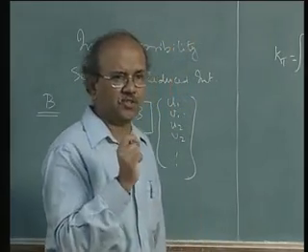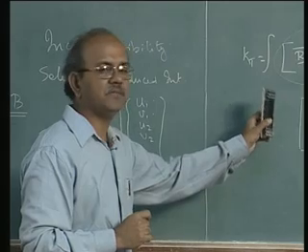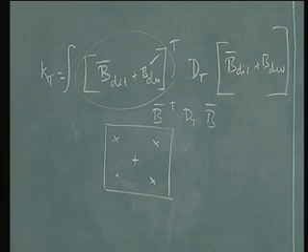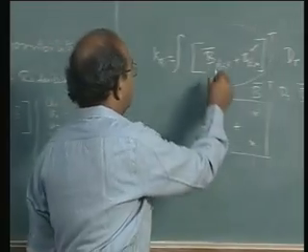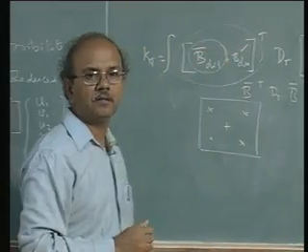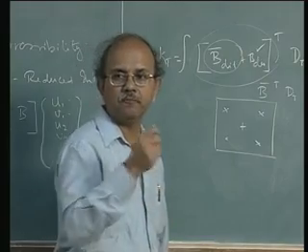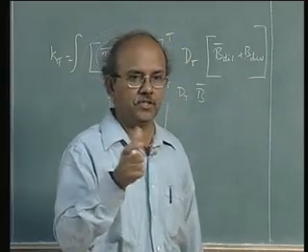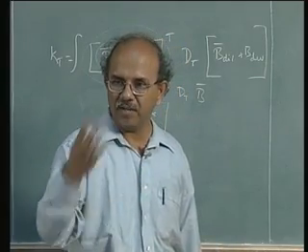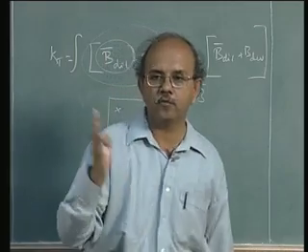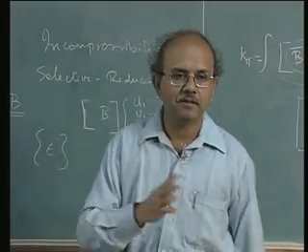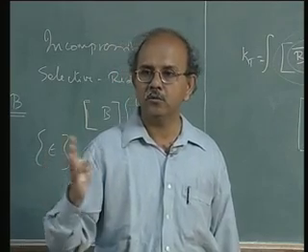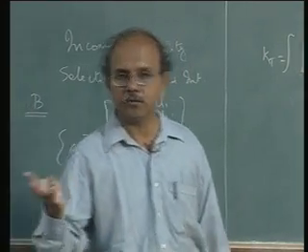The essence of the story is that the B term is split into 2 parts, and that the culprit dilatational part is the one where maximum emphasis or maximum attention is given. This is what I explained initially when I said that there are 2 parts to the K matrix itself, when I look at it from aspects of D, and that one fellow who's the culprit is going to make one of the terms infinity when nu is equal to, say, 0.5.